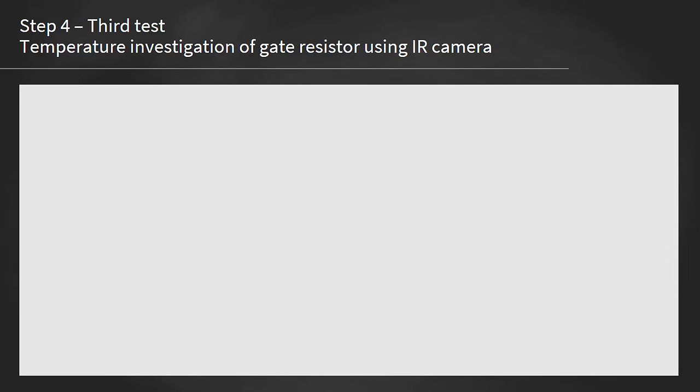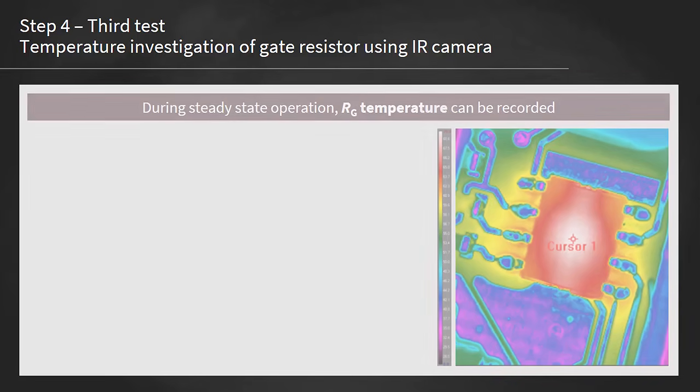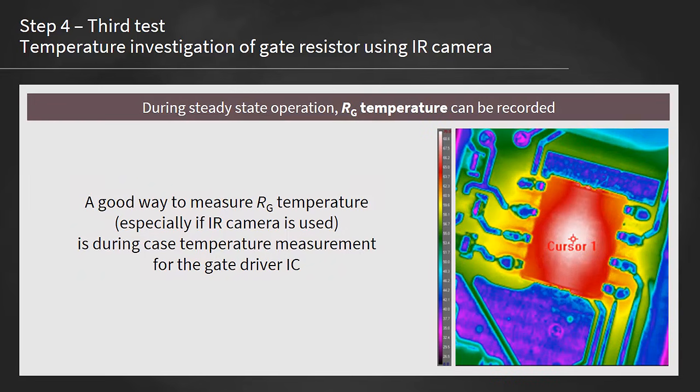The gate resistor temperature should also be measured at steady state. A good way to measure it, especially if a thermal camera is used, is during the case temperature measurement for the driver IC.